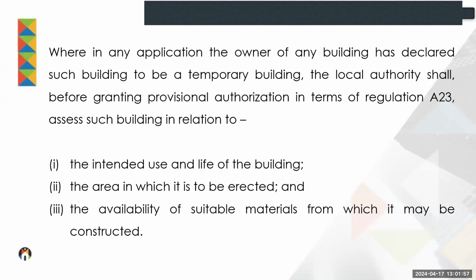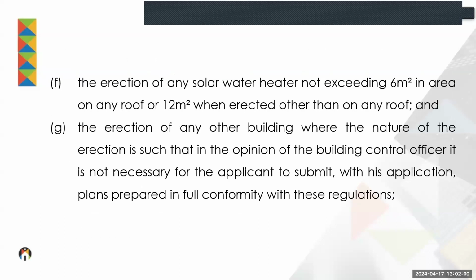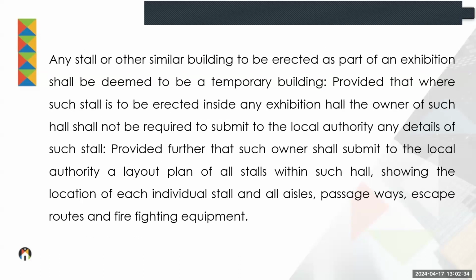Just going back to the minor works buildings, remember that minor works have to comply with the national building regulations or with the standards requirements. So that's why I look at an open carport now, for instance. If that is out of steel, for instance, steel design is not covered by the national building regulations, and there's no deemed-to-satisfy in the 10-400s. That means that that steel structure needs to be the subject of rational design, and in many cases, it needs full submission of building plans for that matter.